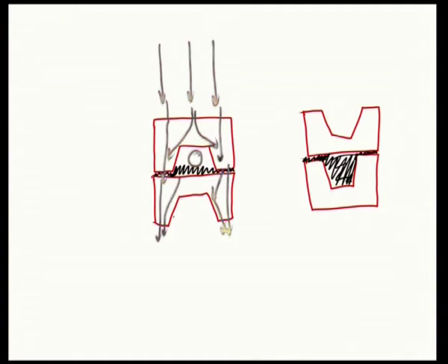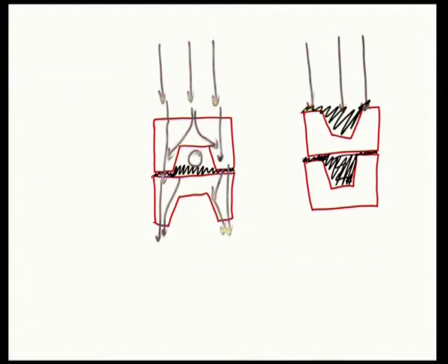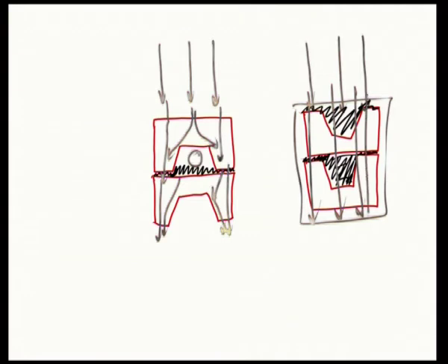What happens to a brick when the frog is laid on top? Load is coming like here. Since this whole thing is filled and there is mortar here as well, so when the load is acting, since this whole thing is a monolithic structure, the load tends to be distributed more uniformly.